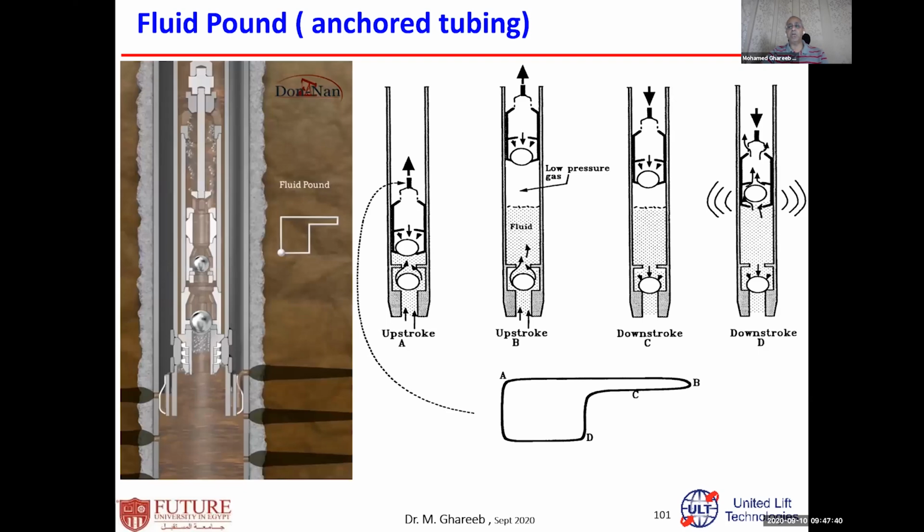It's a fluid, especially if this fluid has very low API gravity and high viscosity. The viscosity is very high, the gravity is very low. Then it works like some chalk downhole, the plunger is hitting the face of the fluid. All this hitting shocks back to the traveling valve, back to the rod string, back to the pumping unit, and can easily damage the pumping unit.